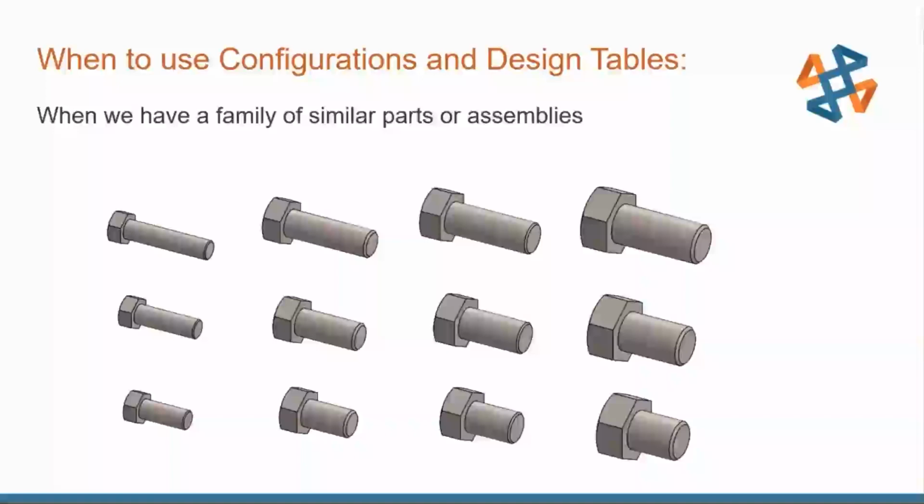But of course, you can use configurations and design tables in a lot of different ways. Maybe you want to simplify a part. Configurations are great for that. Set a part up for finite element analysis and remove geometries that aren't critical to the analysis. Also another good example of configurations and design tables.